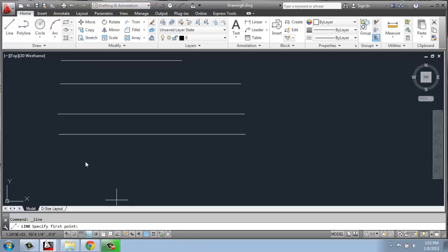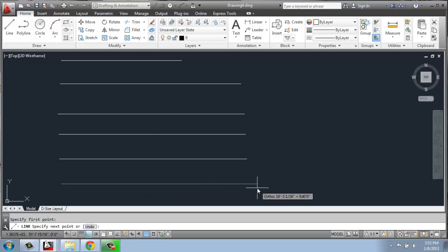If we're getting a little more specific, if I'm typing in, let's say, 15 feet 6½ inches, I have a few options. So I can do 15 feet 6 and then 0.5 for 6½ inches, or I could do 15 feet 6. But to do a fraction, what I have to do is a little hyphen there, and then a 1/2. Okay, so take a look at that.